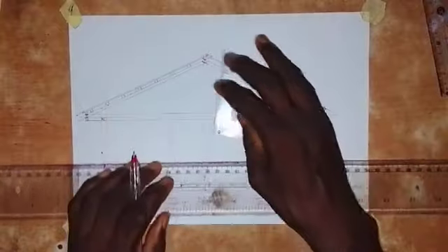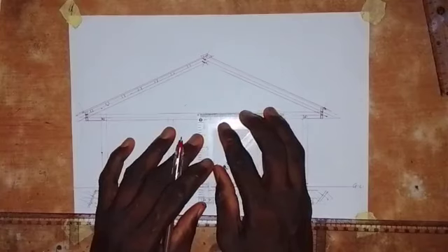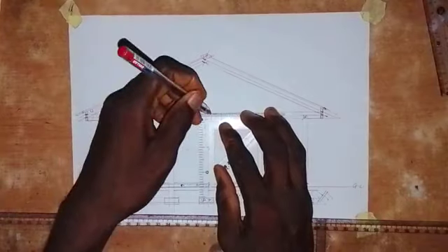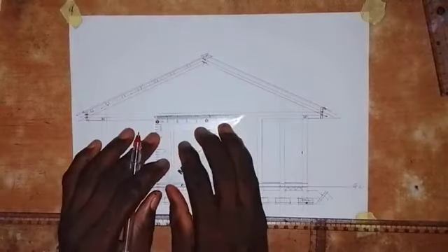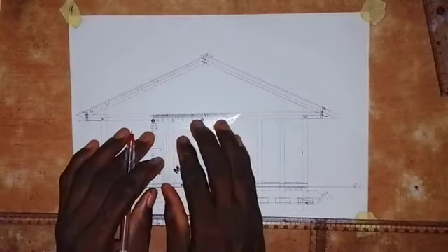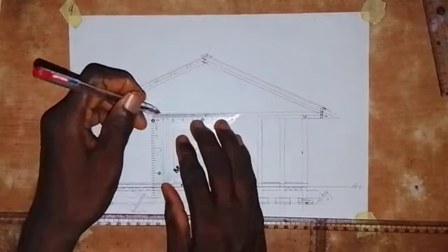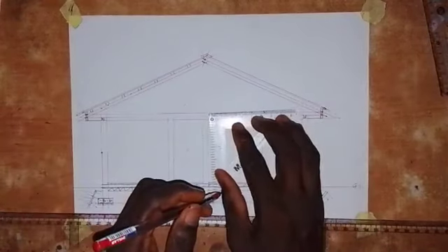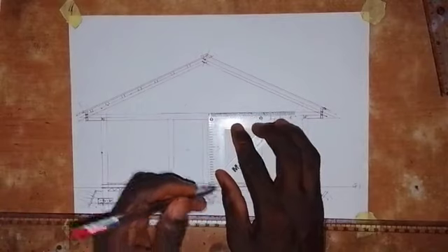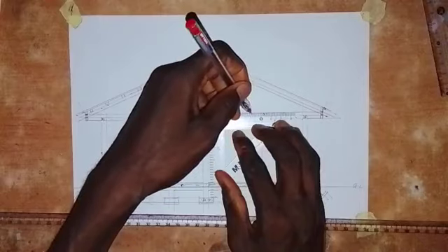So I'll just take the line. So mark that middle point, and then I will take something like 5 millimeters to the left side here and 5 millimeters to the right. So I'll move away a little bit, like 50 millimeters away. Okay, and then take 10 millimeters in here. So I'll come to this side from this point. So take 50 millimeters. So this is 15, and then take 10 millimeters inward.